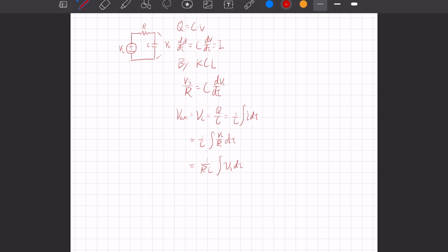So according to the amplifier formula, Vout equals (1 + R2/R1) times Vin. So a circuit with R2 divided by R1 equal to 9 is needed. After combining the two circuits, we get the circuit part we need.